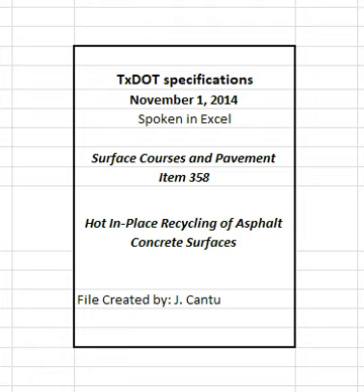1.3 Repaving. Repaving combines either recycling or remixing with an overlay of new HMA placed immediately after the recycled mixture. The new HMA layer is placed directly on the recycled layer, and both are compacted simultaneously.